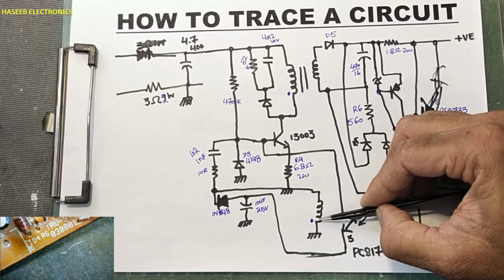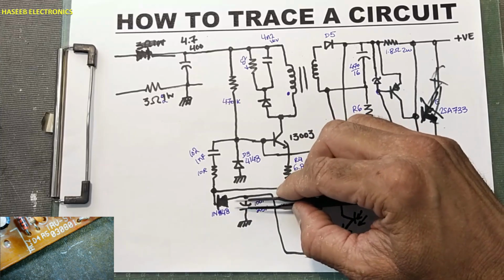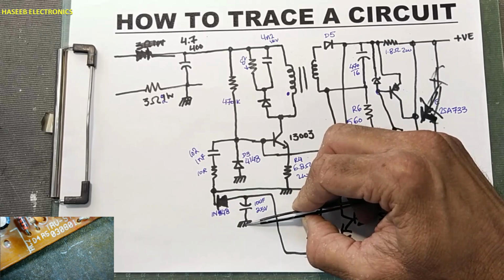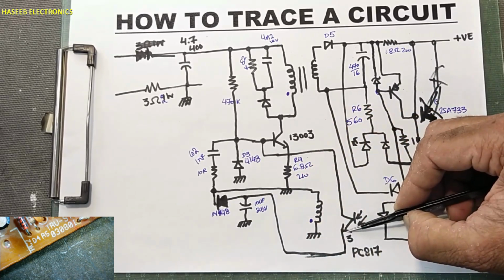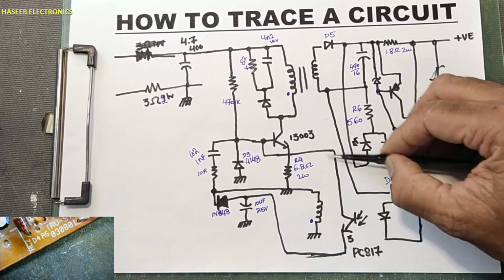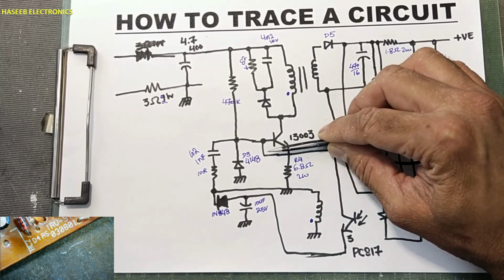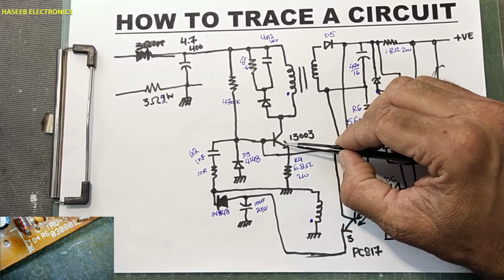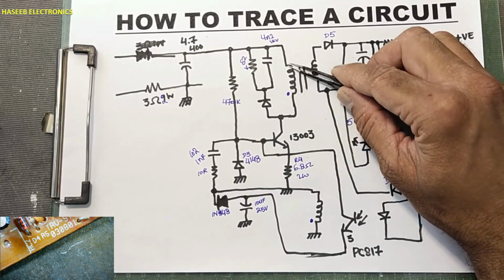Now this voltage, the auxiliary winding voltage, is being rectified and started to charge this capacitor. Now this capacitor is in opposite polarity. Positive end is grounded, and the negative terminal, this side, is connected to the emitter of this transistor. When voltage is maintained, this negative level will reach the base. NPN transistor base will become negative. It will pull down to turn off the base to emitter junction. When the base to emitter junction becomes non-conductive, at that time this current will stop.